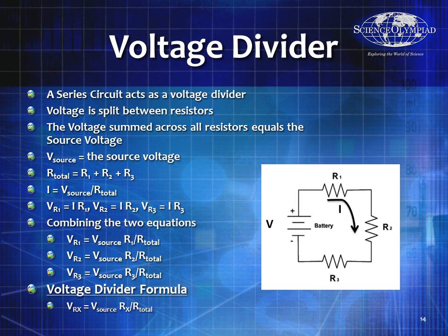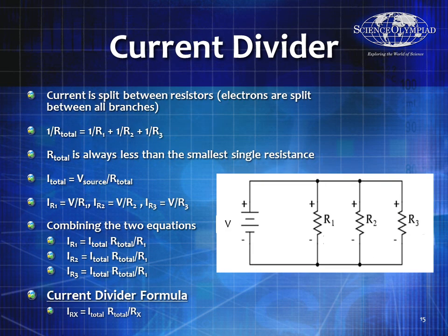Now, let's say all three of them had the same resistance. Well, then it's real simple, because I know if this is like 9 volts, I hooked up to a 9-volt battery, guess what? I got 3 volts here, 3 volts here, 3 volts here, because it's going to be exactly the same. So it allows you to make very quick calculations, and it also allows you to double check your work, because if you've got a bigger resistor and it's got less voltage than one that's a smaller resistor and it somehow has more voltage, you know you probably made a mistake somewhere.